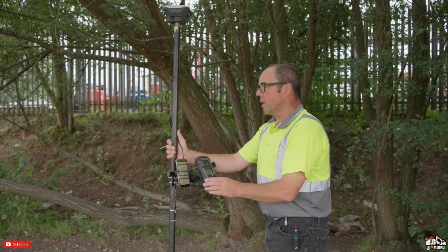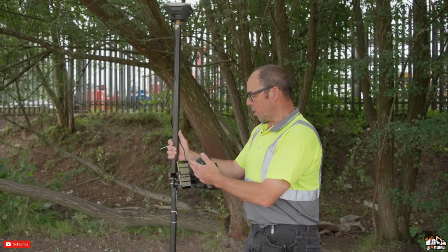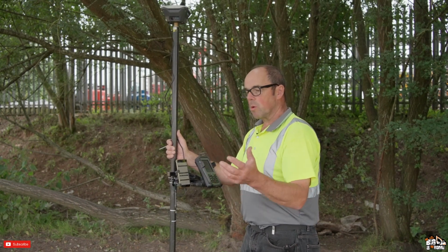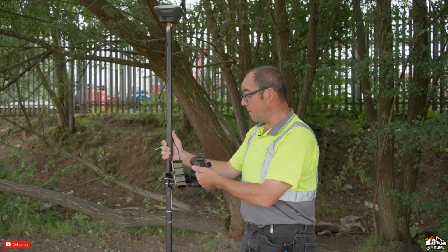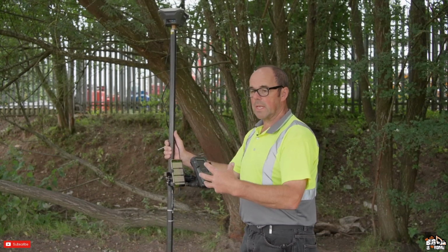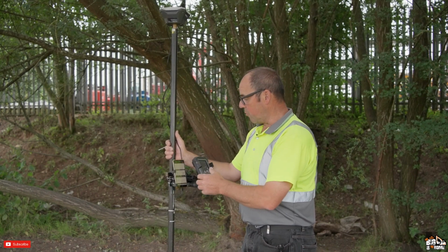The weather also, I think Lee's mentioned the weather. The solution from float to fix will drop out if the cloud cover gets too much, and also if there aren't enough satellites. Currently we're tracking 25, we were tracking 27 up there. If that drops down to too few satellites, there isn't enough of them to get a good enough signal, and it'll drop to float then.